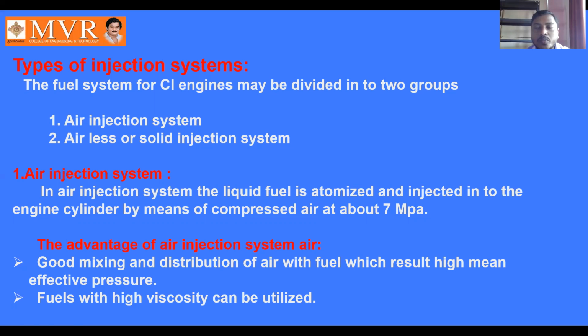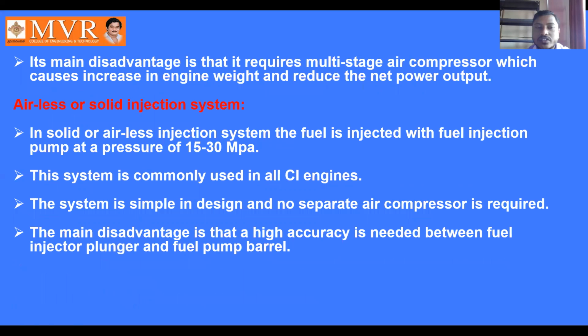Good mixing means both the air and fuel should be mixed and distributed in the engine cylinder, which gets a high mean effective pressure. Fuels with a high viscosity can be utilized for this air injection system. Its main disadvantage is that it requires a multi-stage air compressor.